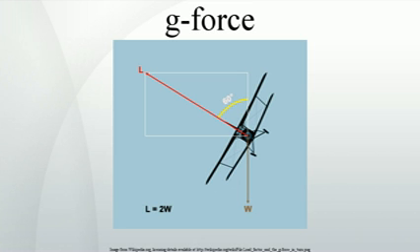In aircraft particularly, vertical g-forces are often positive, forcing blood towards the feet and away from the head. This causes problems with the eyes and brain in particular. As positive vertical g-forces are progressively increased, such as in a centrifuge, the following symptoms may be experienced. Grey-out, where the vision loses hue, easily reversible on leveling out. Tunnel vision, where peripheral vision is progressively lost.